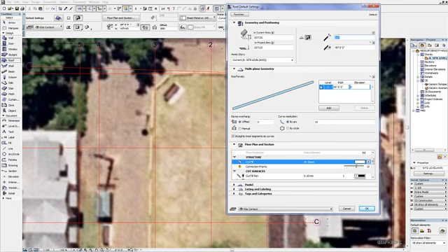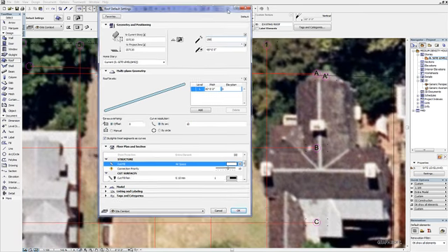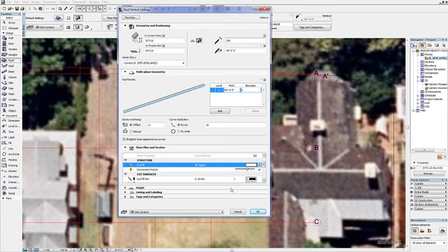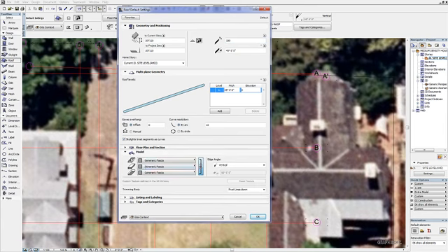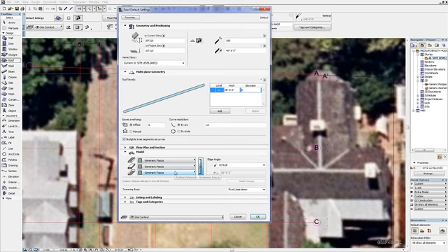So what we're going to do is click on airspace, which we've just done, and change this to 150. 150 is a judgment that I've made based on the photos that the roof is, say, 150 thick. Now if we keep going, in this section we've got the model color, which is currently sitting as generic fascia. If you wanted to change the model color to something else, by all means, you're welcome to do that. I'm just going to leave it at the default, which is generic fascia.